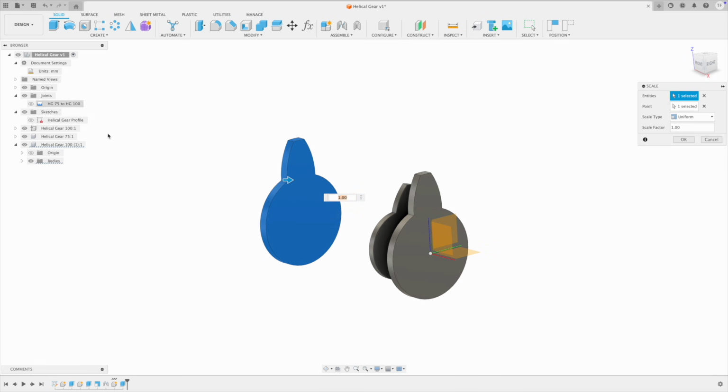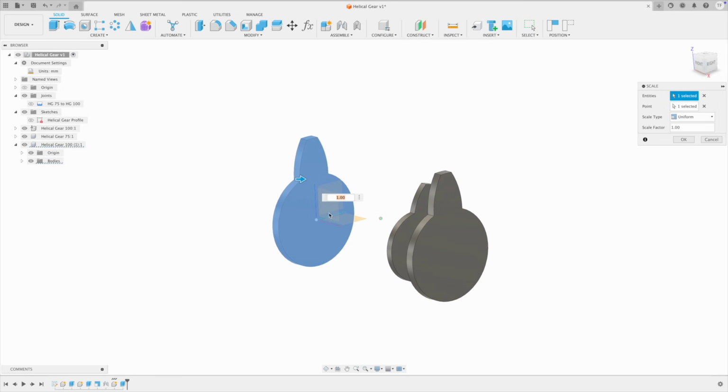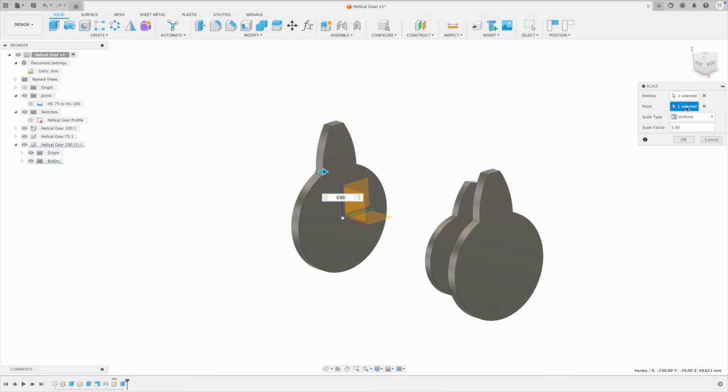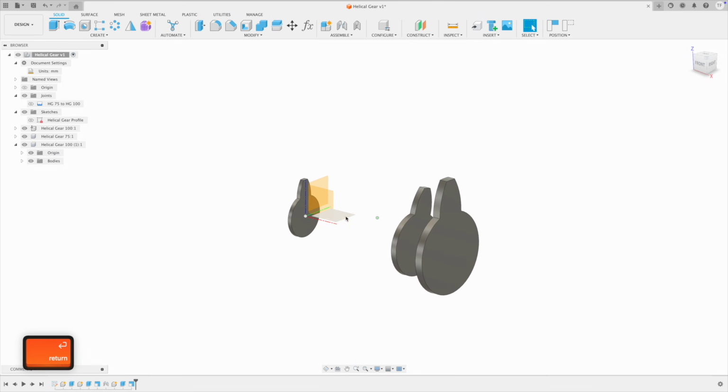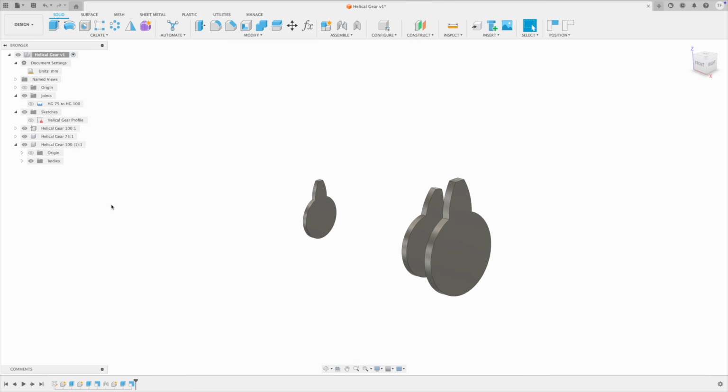Remember, if we turn on the original origin, it's way over here. We don't want that. That's kind of our master origin for our entire part. Let's just turn on this origin, which always moves with our part. So let's go point. We're going to pick that right there. We're going to move it down to 0.5. Very good. Excellent. We can hide that origin right now.